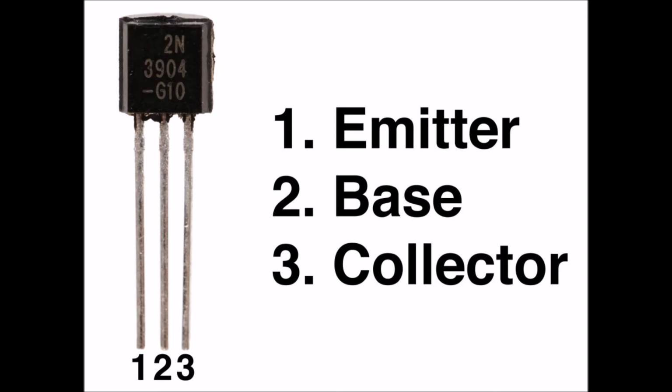The transistor exhibits a relatively high input impedance, while its output impedance remains low. For this reason, the common collector circuit can take the place of a transformer when we want to match a high impedance circuit to a low impedance circuit or load. A well-designed emitter follower circuit can function over a wider range of frequencies than a typical wire-wound transformer can.